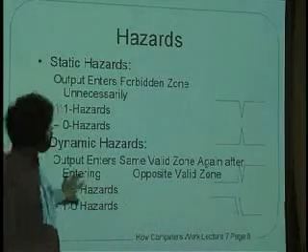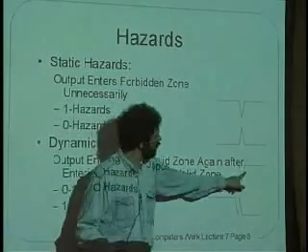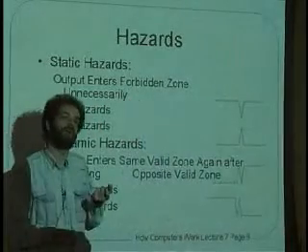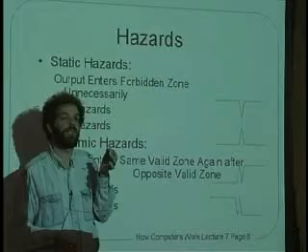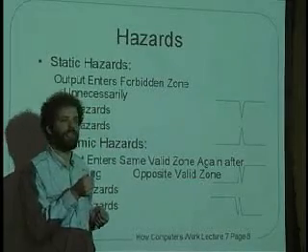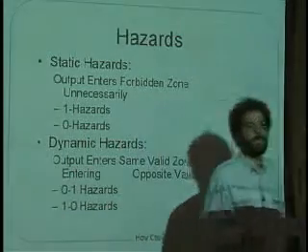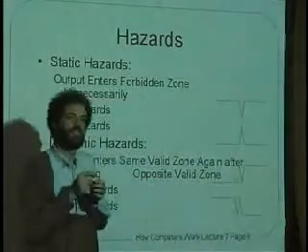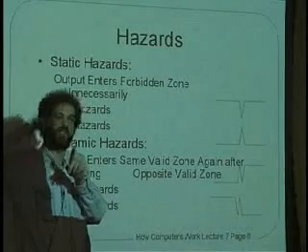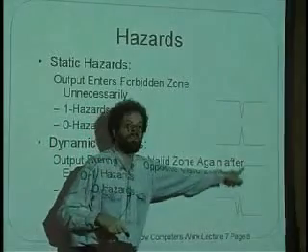And there's also other kind of hazards which are called 0-1 or 1-0 hazards that look like this and involves a kind of a hesitancy in terms of making a transition between a 0 and a 1 where it sort of bounces up and down a few times. Many of you have, of course, had experience with pressing the set buttons on a clock. Like, you know, there's a set button here to set the minute and the hour, and if the switch has a little bit of dirt in it, right, then the clock suddenly jumps a whole bunch, right, because the set button has kind of gone up and down many times in order to, you know, increment something. That would be a hazard that's kind of like this, okay?